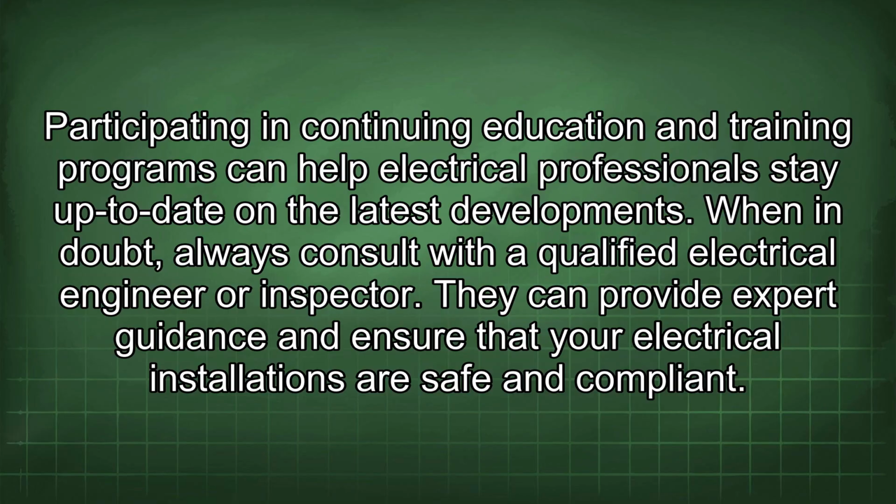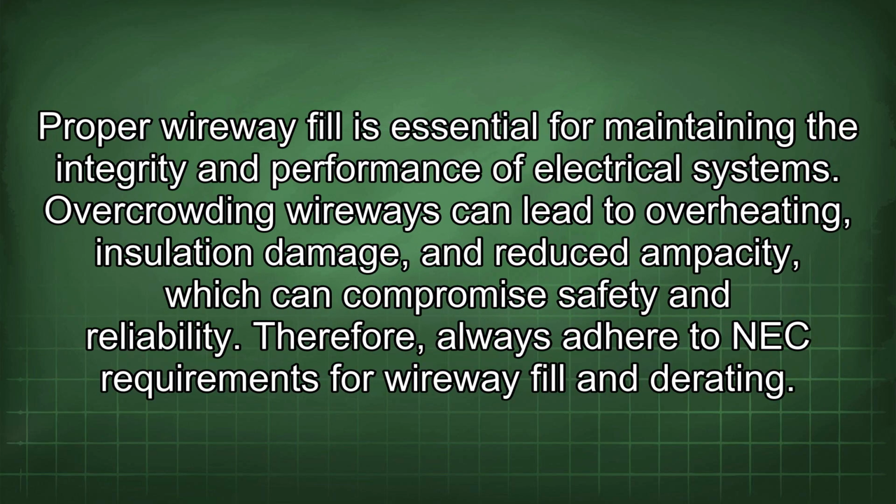When in doubt, always consult with a qualified electrical engineer or inspector. They can provide expert guidance and ensure that your electrical installations are safe and compliant. Proper wireway fill is essential for maintaining the integrity and performance of electrical systems. Overcrowding wireways can lead to overheating, insulation damage, and reduced ampacity, which can compromise safety and reliability. Therefore, always adhere to NEC requirements for wireway fill and derating.